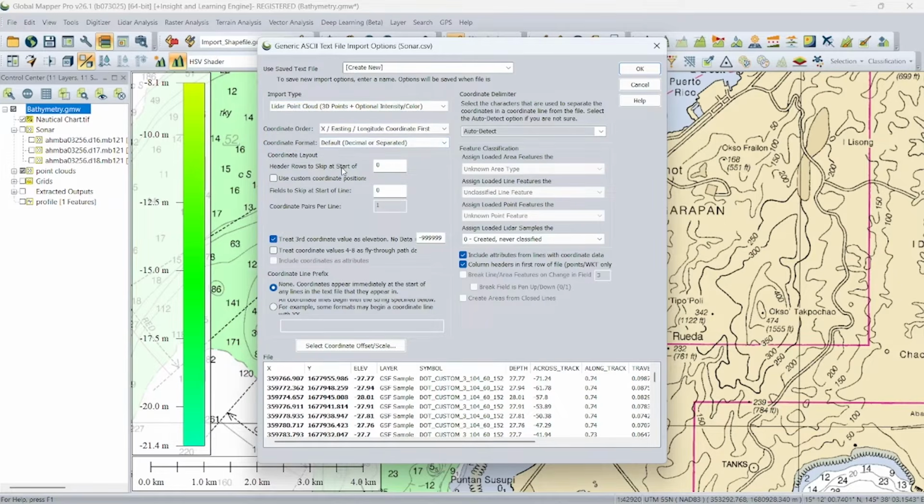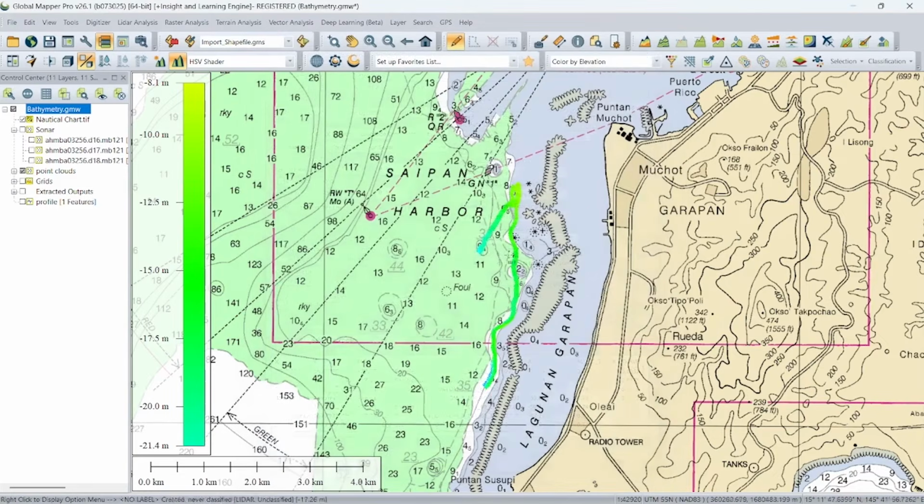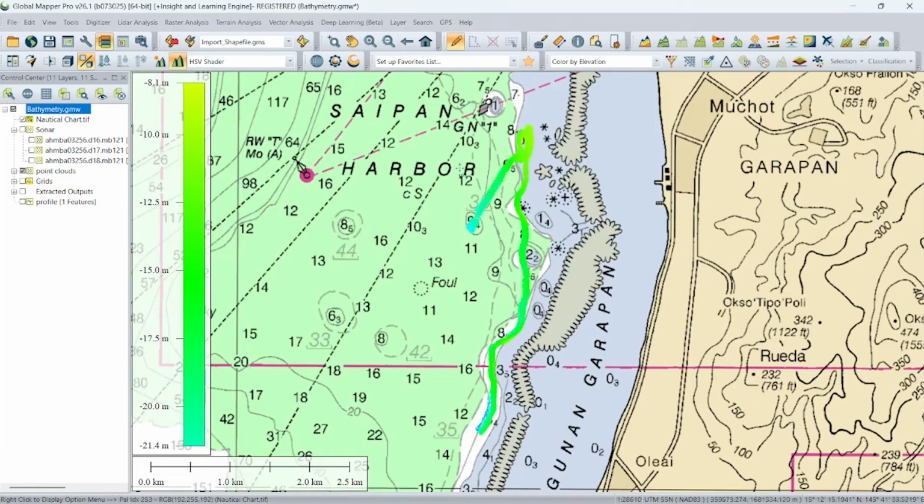And what this allows me to do is have a lot faster rendering when working with this particular type of data, as well as having access to all of the point cloud specific tools contained within Global Mapper. So I've actually already imported this, so I'm going to just close this dialog. And that's what we're currently looking at here, is this point cloud layer that I created through combining these 3 separate files containing the results of the multi-beam survey.